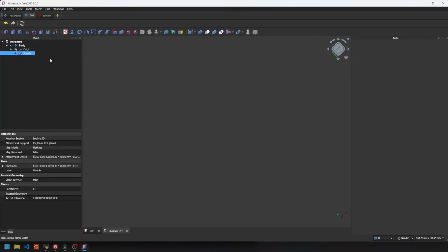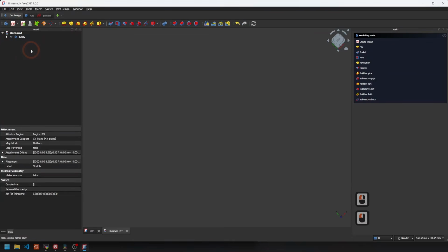For example, you have something created in Blender, which is maybe some organic 3D object, and you want to combine it with some object which you have created with the part design, and you want to do some basic Boolean operation. You can do that here in the part workbench. You can also create different kinds of solids here, like spheres and cylinders. In the part design workbench, you're always focusing on one body.